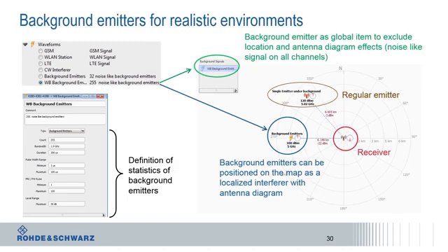In this example here, you can see that I've defined 255 emitter signals within a bandwidth of 1.9 GHz. And I've also defined a certain duration. For the statistics, you can give the ratios of the pulse repetition frequency to the pulse duration, and you can also give a level range for where you want the radar signals to occur.